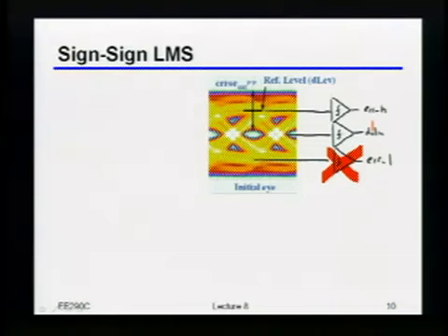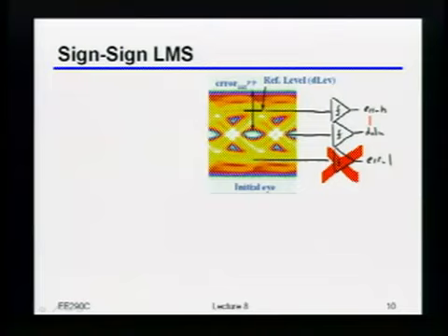What you'll usually do is deserialize the data and the error itself, and do some processing in the lower frequency domain on those error and data samples to figure out which direction you should go. Then, as an example, just average over the entire block, maybe a block of 10 or 20. And based on the entire block, only if a bunch of them said to move one direction or the other, only then do you really apply the update. So there are a lot of details on how you build these things and do the filtering to reduce the dither that you get.